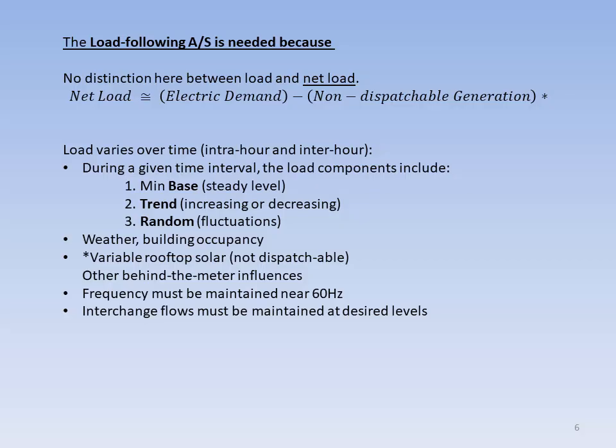Load following is a service provided by generators that change their supply output in response to changes in demand. In this context, the demand we are talking about is net load. Net load is the combination of electric demand from consumers and non-dispatchable generation. Non-dispatchable generation is mostly supplied by rooftop solar.